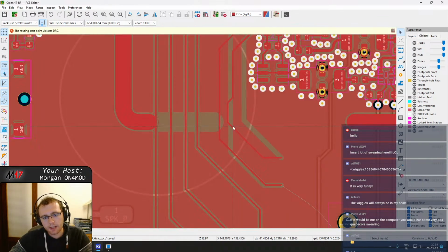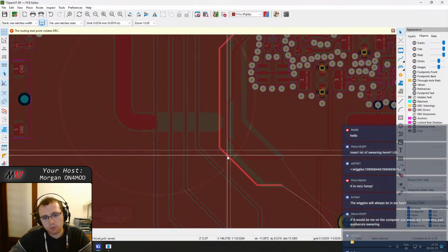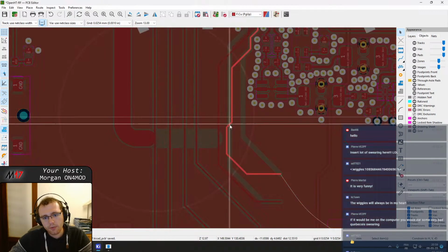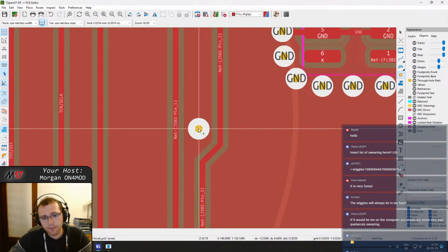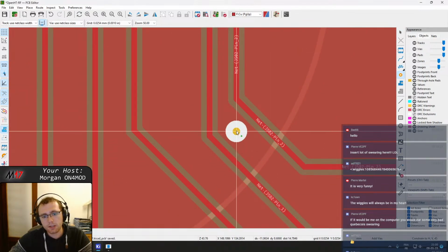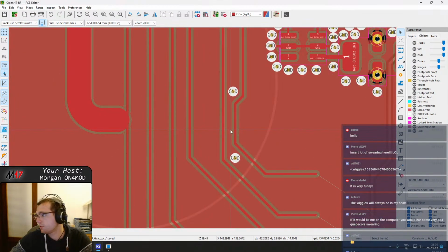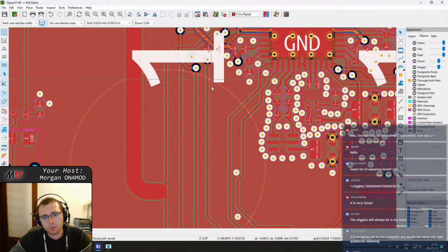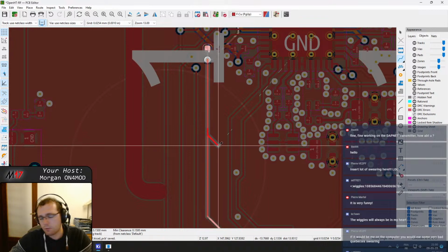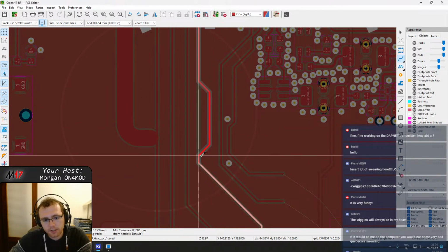So we want to have a neck around where it goes through the shield, but not before and not after, because it will allow us to place vias right here, for example, and right here. So this is all we need, and it also is gonna make a smaller opening in the shield, which you always prefer to have, the smallest openings possible in a shield. Otherwise, it's not gonna do its job properly.